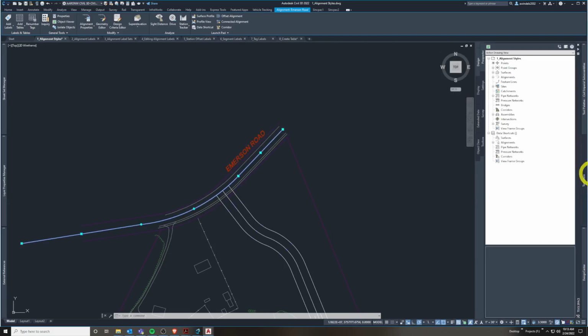Another reminder is that you can get to these in the file tree, alignments. This is very critical. Just keep drilling this in. They populate here. We have a bunch of different types of alignments. Centerline alignments are generally the center lines of roads. So alignments are, as we learned in Chapter 5, the backbone and baseline for what many things are designed off of. They're their home base, the baseline.